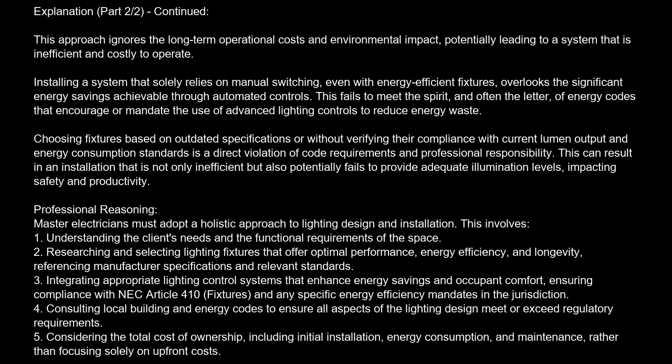Integrating appropriate lighting control systems that enhance energy savings and occupant comfort, ensuring compliance with NEC Article 410, fixtures, and any specific energy efficiency mandates in the jurisdiction. 4. Consulting local building and energy codes to ensure all aspects of the lighting design meet or exceed regulatory requirements. 5. Considering the total cost of ownership, including initial installation, energy consumption, and maintenance, rather than focusing solely on upfront costs.